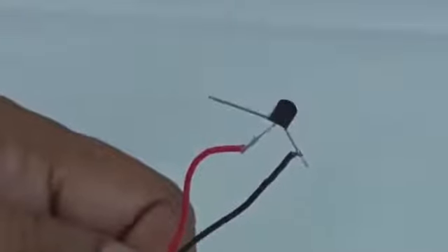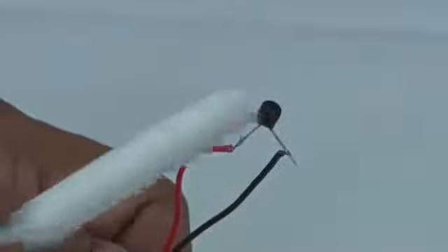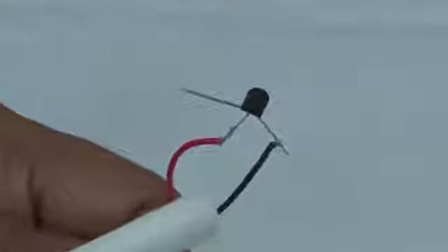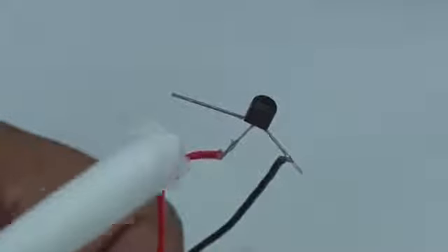This is a low power one, used for small currents, and then you have other kinds of transistors where the casing is metallic and full cylindrical, and from the bottom 3 leads come out. On the circular top there is a notch from which people find the first lead, second lead, and third lead, and then the data sheet will say which is emitter, which is collector, and which is base.